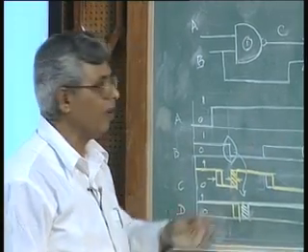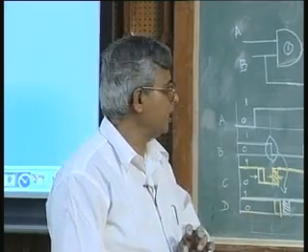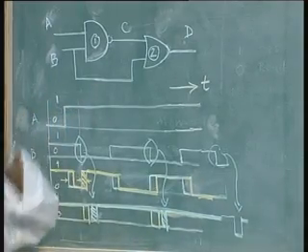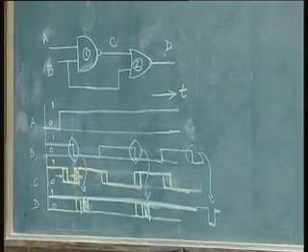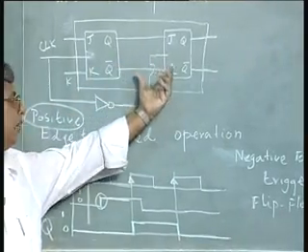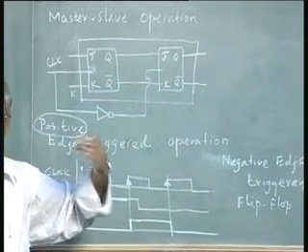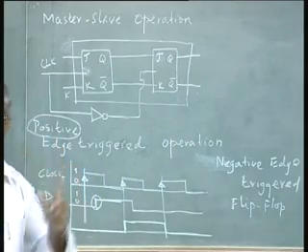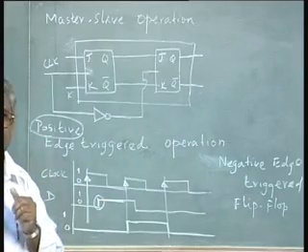Now, in edge triggered operation what happens basically is, at each input of the flip flop, here we said simply the JK flip flop has 2, the master slave flip flop has 2 identical flip flops. But in the edge triggered flip flop I said simply, it is very easy to say that there is only one flip flop, so I reduce the hardware. The speed of course is the speed of the propagation I said.